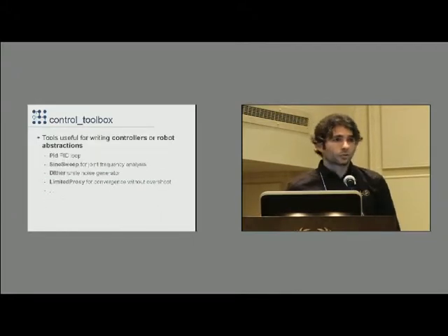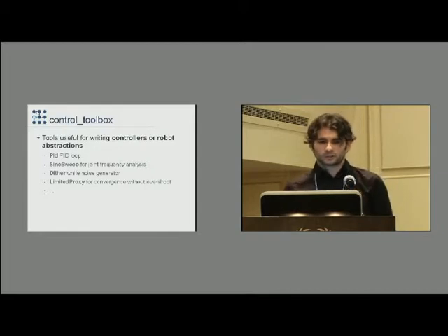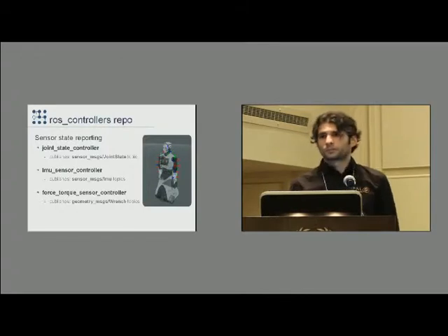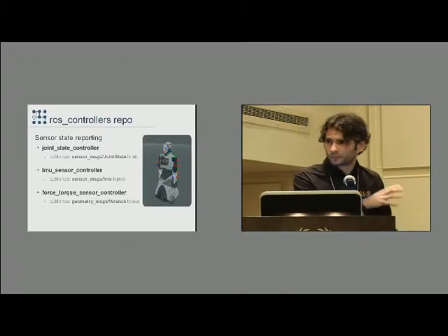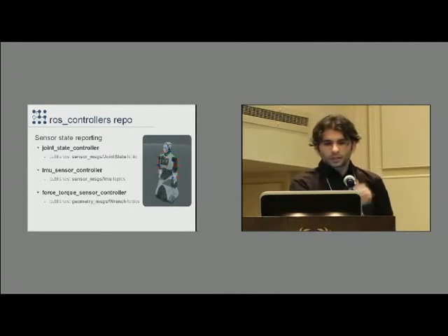There's a package called Controller Toolbox, which you should be aware of because it has some tools that help out in the process of writing a controller. I guess the most used building block is the PID controller, but there's also some other stuff. And there's a repository called ROS Controllers that has controllers that you should go in and see if there's something for you to use, because it has a bunch of controllers that are ready to use.